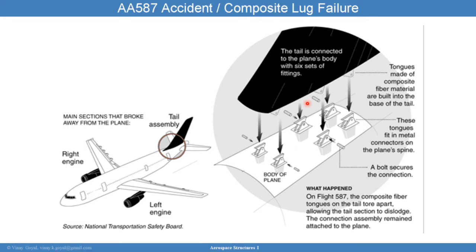Another point I want to make is that the officers' actions did produce a large amount of load into the rudder, and it sounds incredible, but that force was close to 203,000 pounds. It's quite a large load, and it means that the vertical stabilizer did not fail until far in excess of the 100,000 pounds force defined by the design envelope.